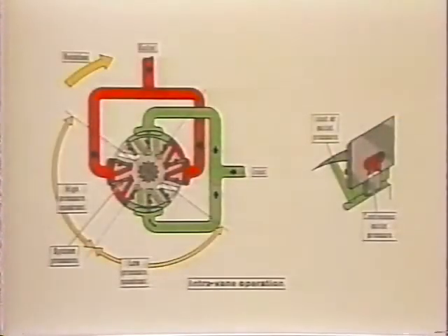Now then, you'll note something different when we examine the cartridge. The two previous pumps had solid vanes, and outlet pressure acted under their entire bottom surface to hold them firmly against the ring.